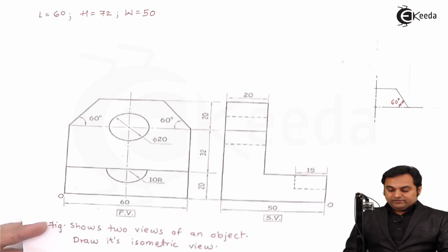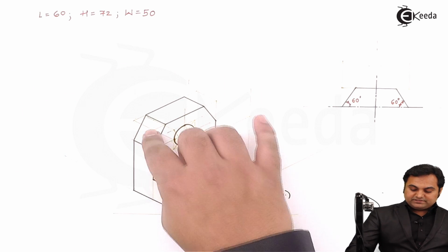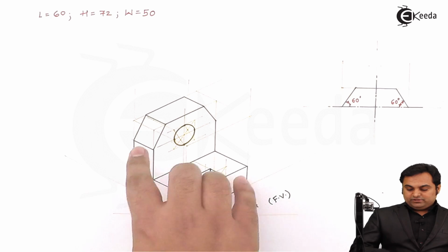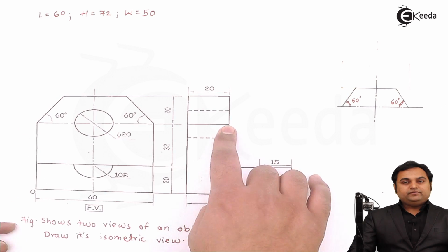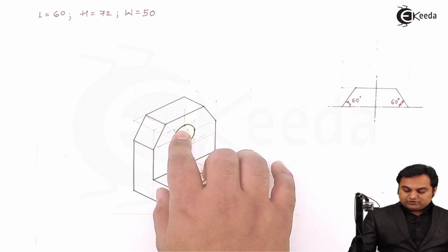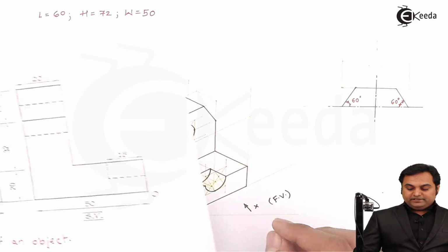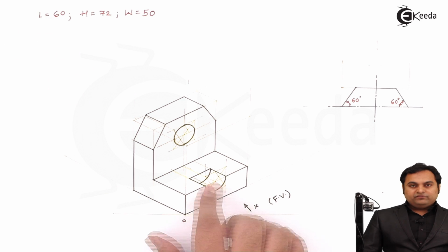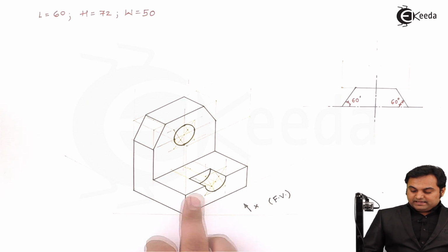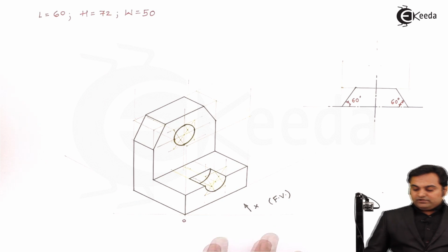Then when we are looking from side, between these two planes, as they are not on the same plane, one is inclined, other is perpendicular, so there is a dark line between them. Next, there is a circular hole. From the side view it is not seen, so it will be hidden, it is hidden here. And then there is a semicircular groove inside this bottom plate, and the semicircular groove is shown with the help of a dotted line. And here we complete the drawing.